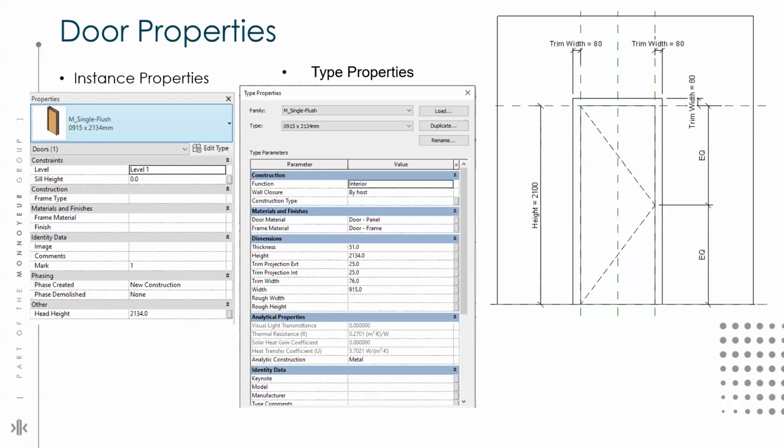So whatever you do will actually come under the new construction phase. If you are doing renovation projects, you can make the whole model of the existing building, mark all of it as existing phase, then start creating something in the new construction phase. With that, you'll also be able to compare and view all of those changes.